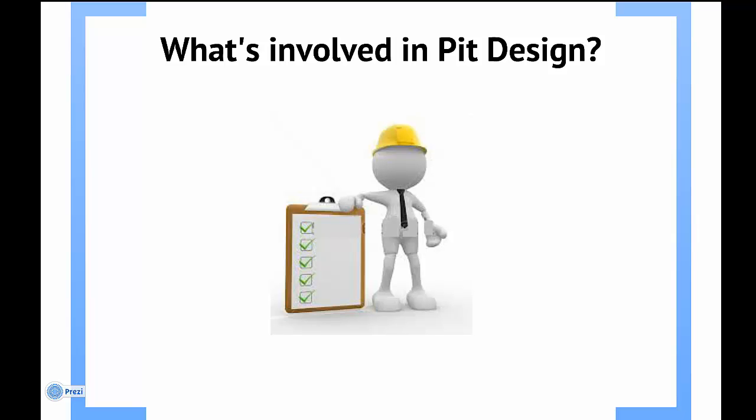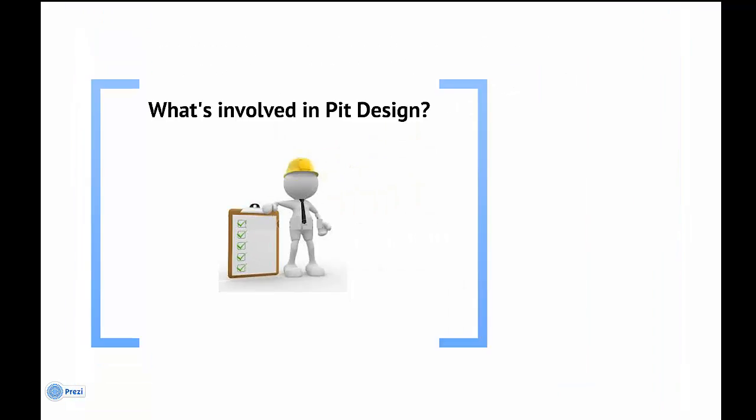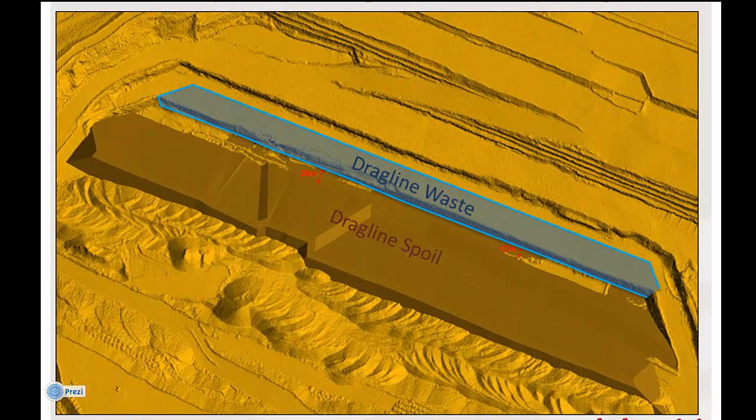Generally, the mid-term planning department have allocated a dragline horizon for the pit, which is based off both the known spoil fit of the dragline and the strategic planning, as an example, what coal uncovery is required. Once the dragline horizon is known, the engineer should complete a strip design using the appropriate planning, geological, geotechnical pit parameters.